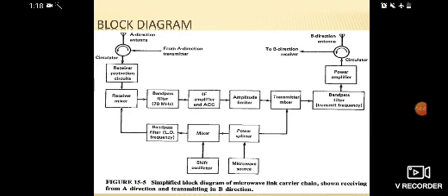Okay, next one is the amplitude limiter. This stage avoids any unwanted amplitude variations and noises by limiting them. Okay, any amplitude variations will be limited to a particular range, and the signal is passed towards the transmitter mixer. This transmitter mixer converts the IF signals into RF signals, that is, from 70 megahertz to 6 gigahertz.